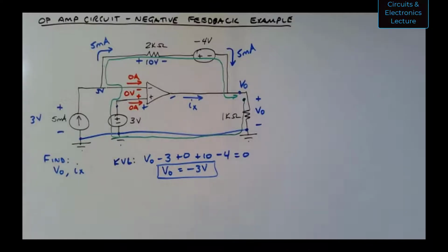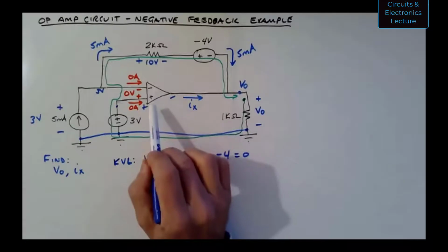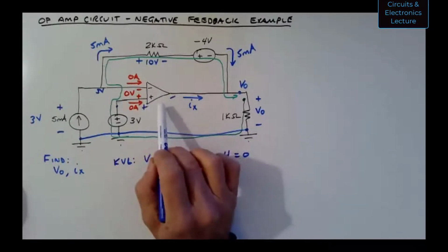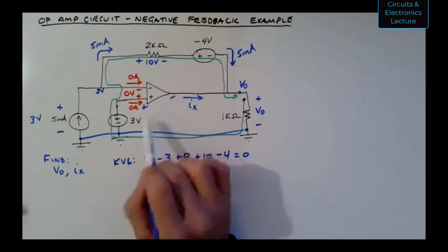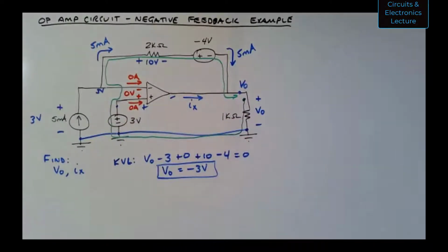So yeah, what I recommend is, at first, you can figure these voltages out later between input and output of the op amp, but at first you don't know them. So your loop should not involve going from input to the output of the op amp. Got it. Okay.